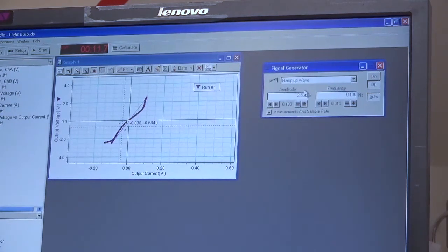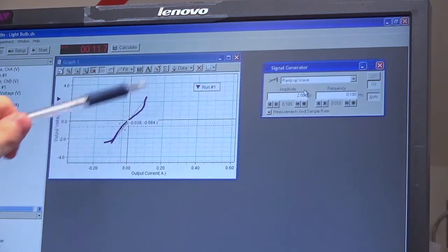So at low frequency, we don't have a steady voltage being repetitively applied to that light bulb in order to render it hot enough to reach its maximum operating temperature and stabilize. Therefore, the temperature is going to keep fluctuating, and the corresponding resistance would fluctuate as well, which leads to a non-ohmic device, characterized by that curvilinear shape over here.